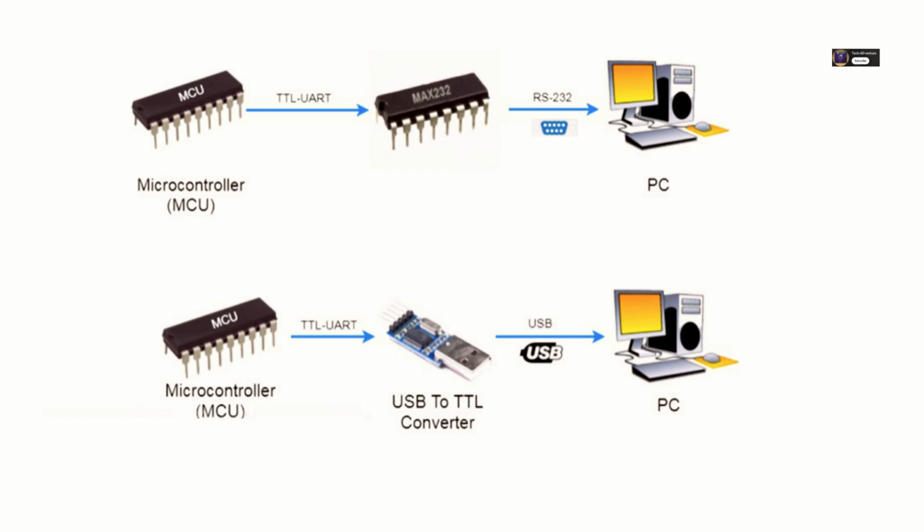If it's not 5V tolerant, you need a simple logic level converter or even just a voltage divider using resistors on the 5V output line to bring the voltage down to a safe level for the 3.3V input. Going the other way, 3.3V output to 5V input often works okay, as 3.3V is usually high enough to be read as a logic HIGH by a 5V device, but it's always best to check the datasheets. Always check the datasheets. Good advice.